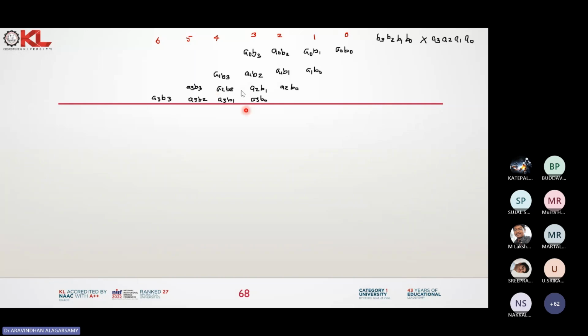In step 2, we'll try to move on to the unoccupied space of the partial products. For example, this fourth one, check this out. There is no partial product on the top. You try to move this column to the top, towards the initial line. Are you getting my point? These three will try to move up here, so that I will start to write A1 B3, A2 B2, A3 B1 like this.